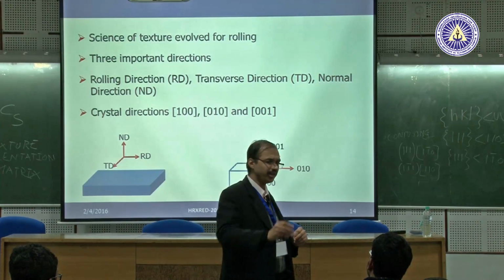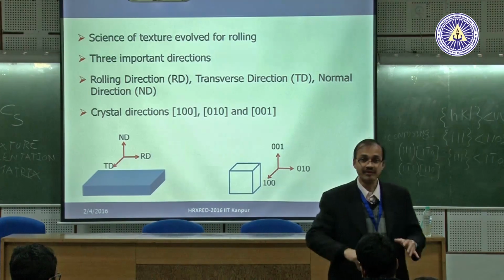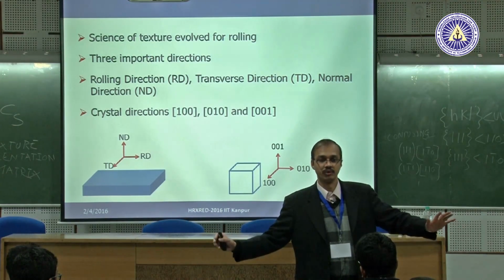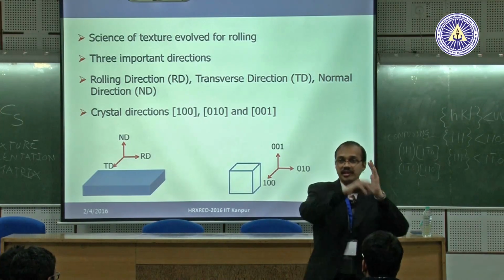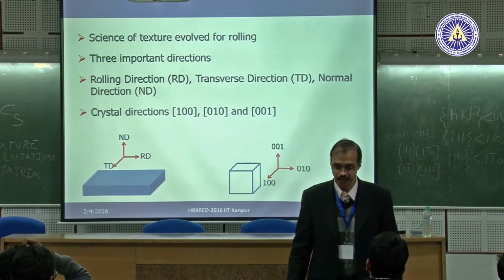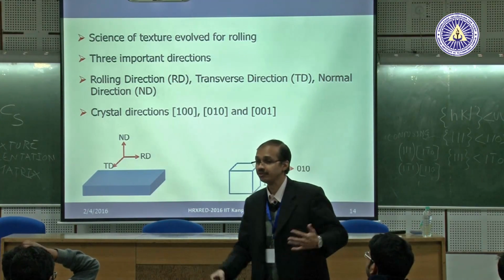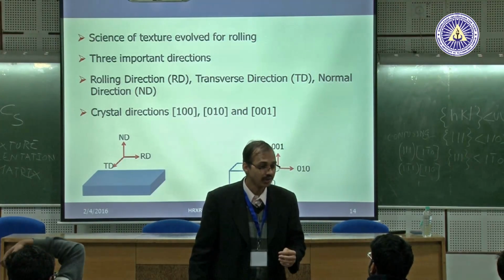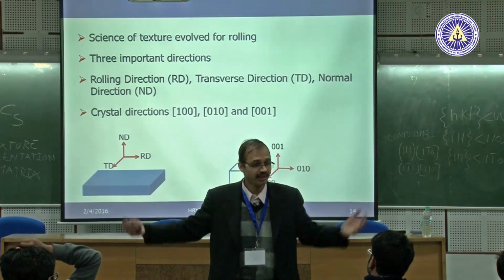Professor Ungar also talked about that. Hey, come on, you don't have a grain size. You have a grain size distribution. So you calculate mean and sigma, and then you say that the grain size distribution is log normal. So when do you get a log normal distribution? Again, you do that with X-ray. Why do you do that with X-ray? Because you are counting many grains.